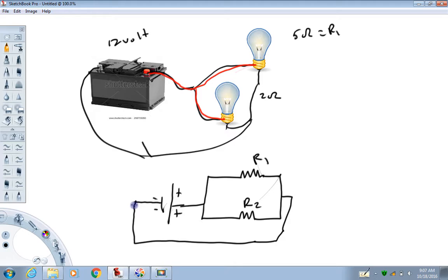Now, in all these circuit diagrams, I really like talking about potential differences. So this is all conducting material up to the bulb. So this is all one potential. I'm going to go ahead and color code that red. Now, the actual value of that potential doesn't really matter. And, just like potential energies, you can actually zero a potential wherever you want. If I decided to call the potential here 0, then red is 12 volts higher.